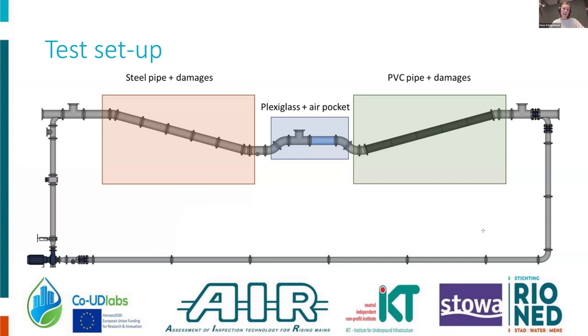So we had a closed loop, and in the upper part a series of pipe segments where the damages were prepared. At our left-hand side, the tools will be inserted. It could be via a horizontal inlet or a T-piece. Then there would be a downward slope of 5 steel pipe segments with several damages applied.